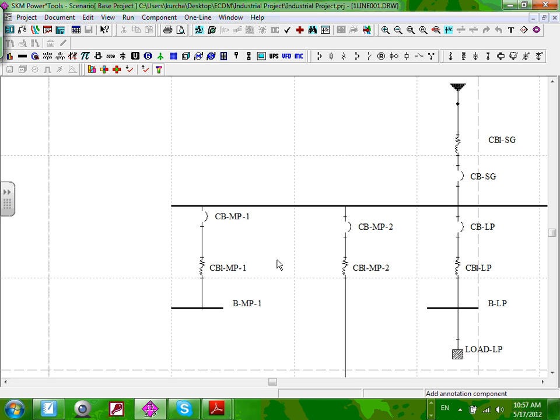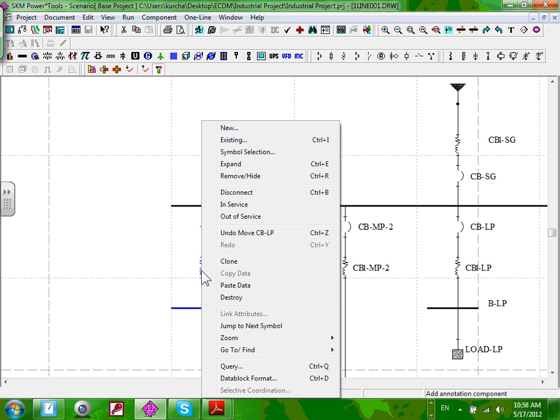Okay. Now let's go clone. I told you it doesn't matter what your belief system, with Chad you're going to clone. So we're going to go right here, pick him up, right to left. One more time. Start here, box them in, right to left. Make sure this is the only thing that's selected, these 3 things. Can I have a thumbs up when you select them? Yep. Okay. You're going to right click, hover over it until you see that little cross there, right click, and clone. Does everybody see the clone?